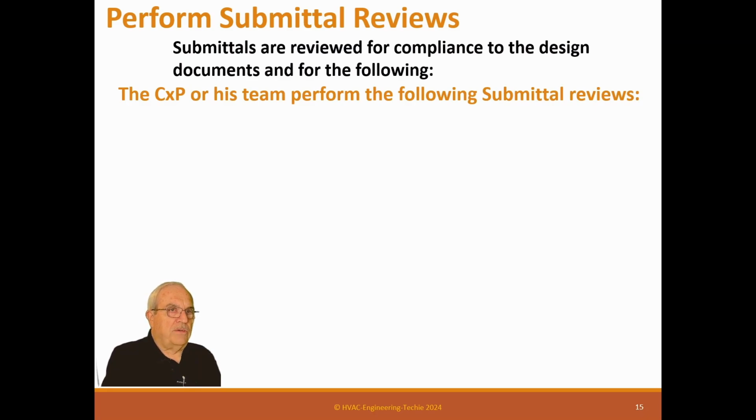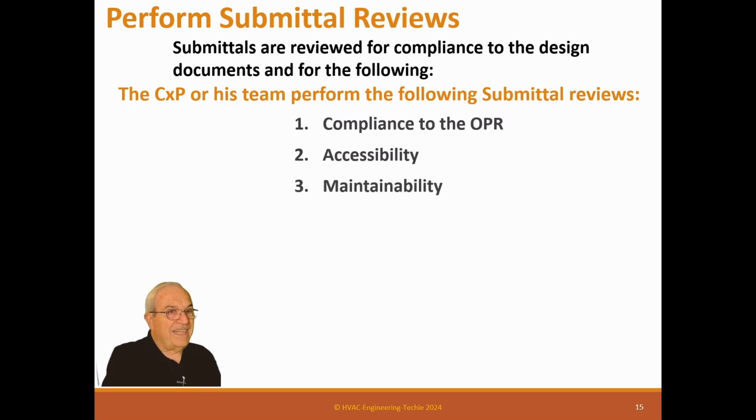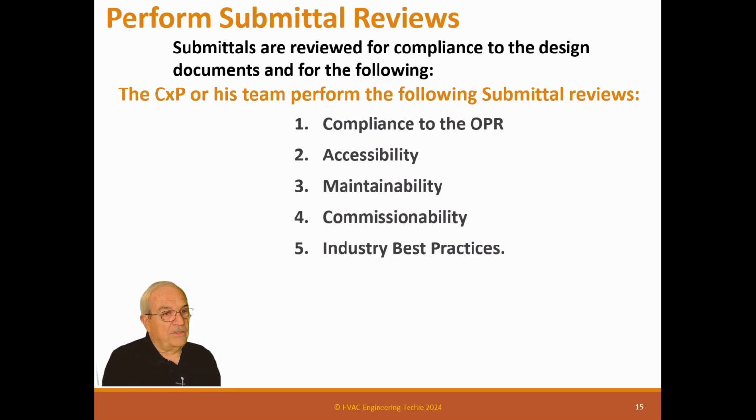So the CXP or his team performs the following submittal reviews: compliance to the OPRs, number one, accessibility, maintainability, commissionability, and industrial best practices. Now, those all seem like catchphrases, but it's really what you're doing. The engineer's looking into this: does it meet what he specified? Is it the right size? Does it have enough BTU capacity? Those are his main concerns.